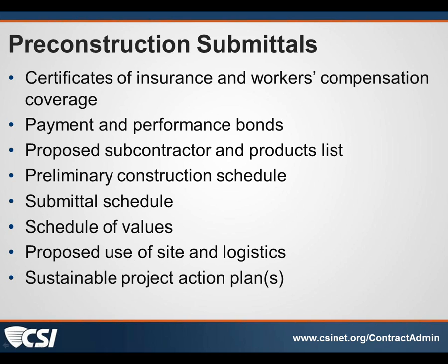So, Doug, I don't know if there's anything you want to add about their tie to the contract, for example, and how they are or how they are not contract documents. Okay. Well, submittals are not contract documents. The contract documents require that the contractor submit submittals so that he can illustrate to the design professional how he intends to comply with the design intent shown in the documents. But those submittals do not become a part of the contract documents.